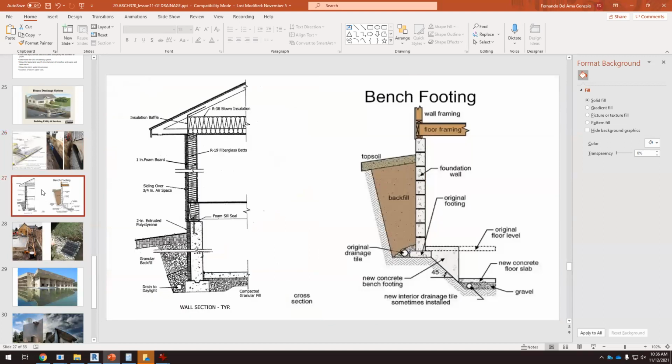collect the water. Okay, so this is outside, it rains. So all the water that filters, we have to collect this water before it affects the basement wall. So that's why we have to place a drainage here at this level, and the water will filter, and then it will be collected by this drainage before entering the basement. So we need a drainage pipe all around the building at the foundation level. If we have a basement, this is mandatory.